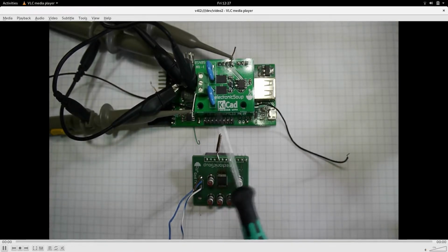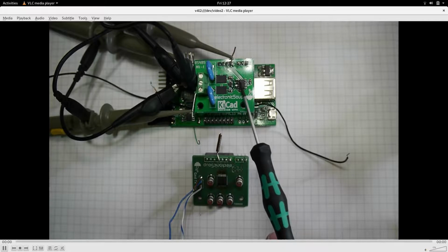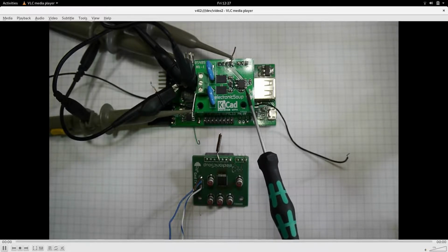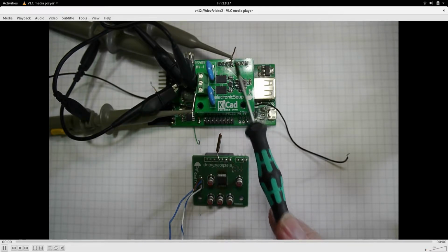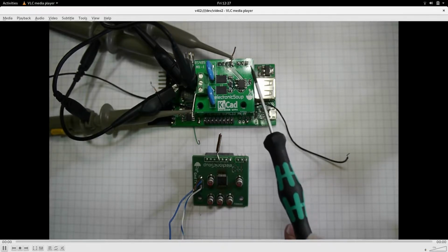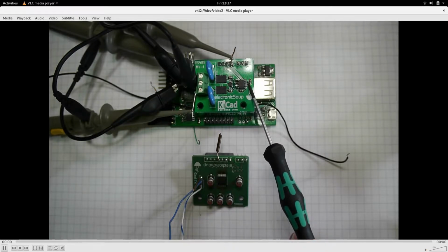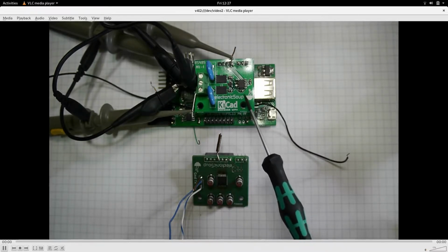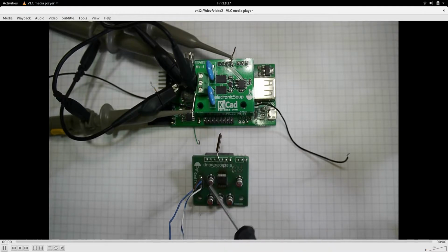So in a similar way, this board features a different transceiver. This is an RS485 transceiver. So basically the same thing is happening on this. This time at pin D0, we're transmitting out a 3v3 serial communications waveform, and this RS485 transceiver is converting that into an RS485 signal on, again, 3 pins, but this time we don't have a transmit and receive.